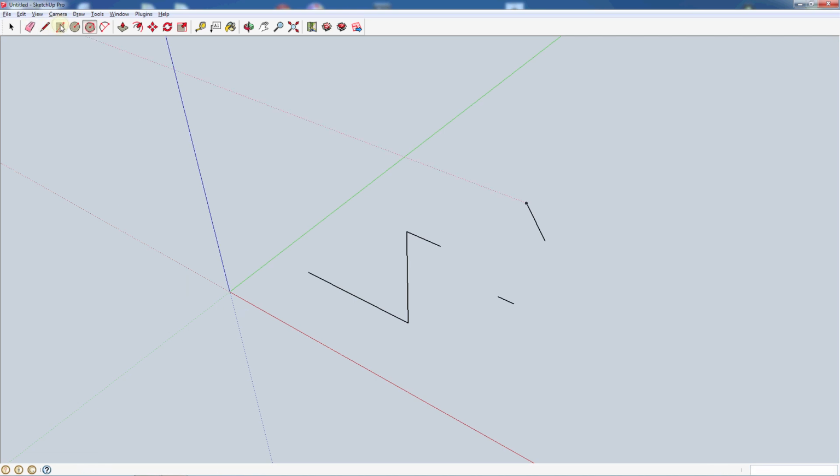All right, we've got other shapes we can deal with besides just lines. We have our square rectangular tool. That very simply will just draw a specific size shape. We can freehand it like I'm doing here and just say, okay, that's the size we want. Or if we want a specific size, we can tell where our start point is. Say I want a 10 by 10 box, so I would type 10, 10, and that appears down in our lower right down here. So again, 10, 10, hit enter, and it will draw a 10 by 10 box for you.